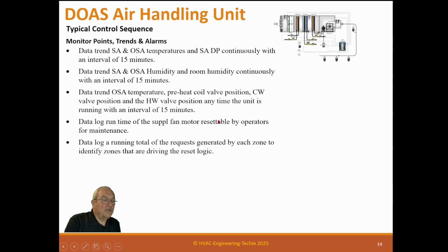Data log a running total of the requests generated by each zone to identify zones that are driving the reset logic. If you have one zone that's always got a problem, then you need to find out what's wrong and fix that problem.